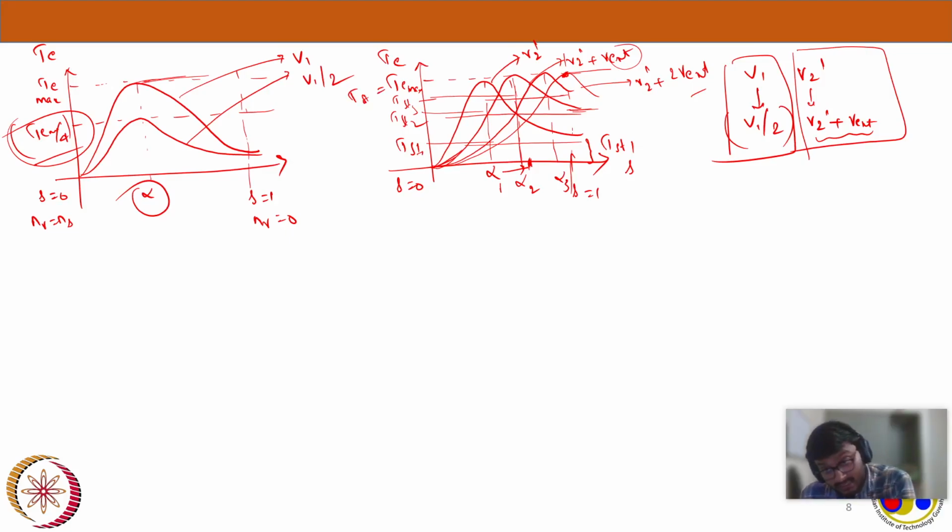But is it a good way? Is it a suggestible way to do it? No, because if you keep on adding rotor resistances, how will your rotor copper losses be? It's proportional. As you keep on increasing resistance, your losses will also increase. So it is not usually suggested to keep on adding these external resistances, but just for improving the starting torque, you can add some resistances and also some improvement in power factor or some improvement in your starting torque.